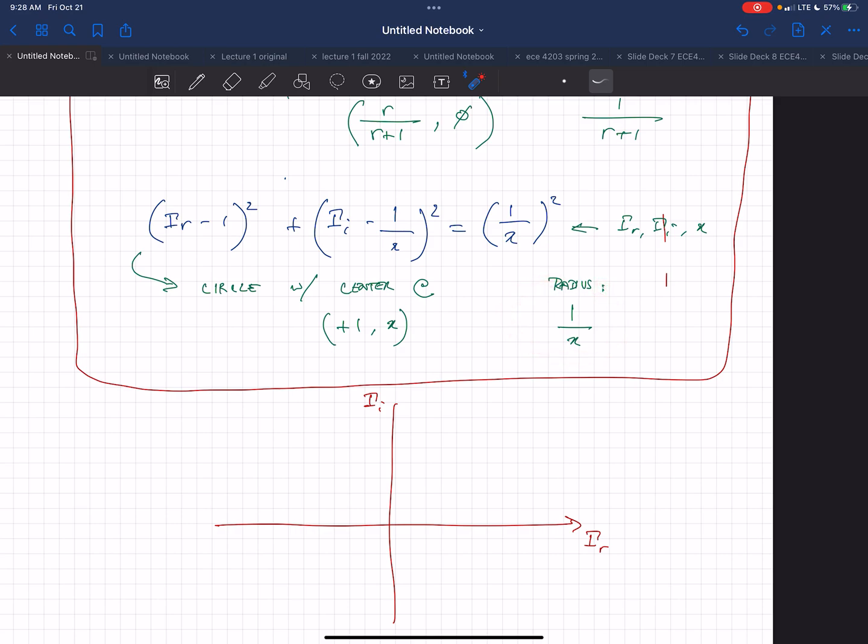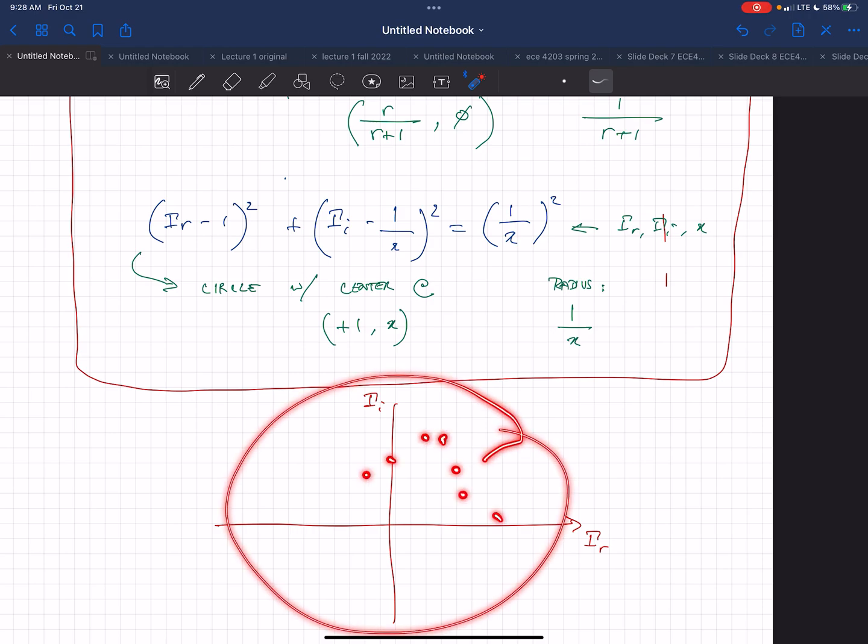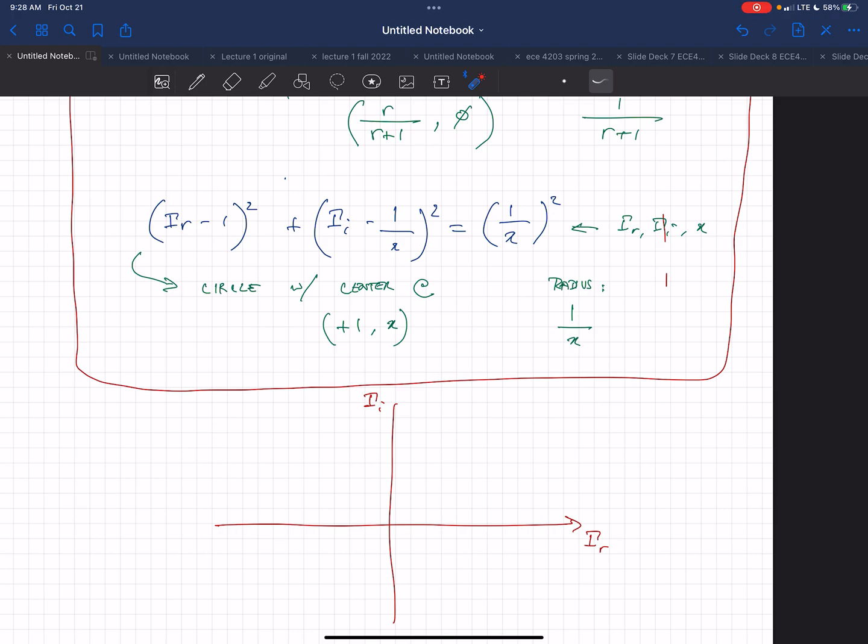Okay, so all this activity up to this point this morning was to be able to have a graphical tool where I can look at the reflection coefficient. At any point here, this is the reflection coefficient plane, right? So what I'm also doing is graphically drawing how the reflection coefficient is going to change as my impedance changes. That's all activities based around that.